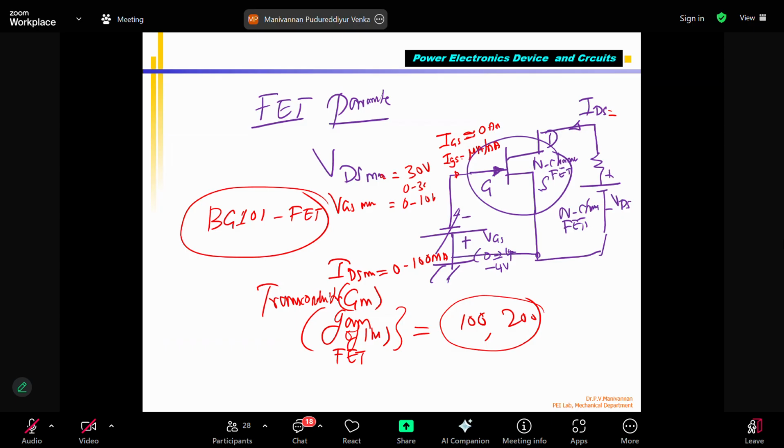This can be connected. Both are connected. So this is the source, drain. This is called RD or load resistance, RL. The VDD, for example, I say 10 volts. Okay, whatever. So this is the circuit of the N channel common source. CS means common source amplifier. This is the circuit. Draw the common source FET amplifier circuit diagram. Explain how the amplifier works.